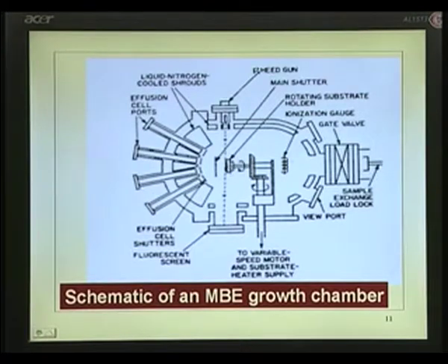That substrate holder can be rotated. We can rotate it, and this entire assembly is for rotating the substrate. Why do you rotate it? So that you get a uniform layer, uniform thickness everywhere. You rotate it like that. So, rotating the substrate holder, then some ionization gauges etc.